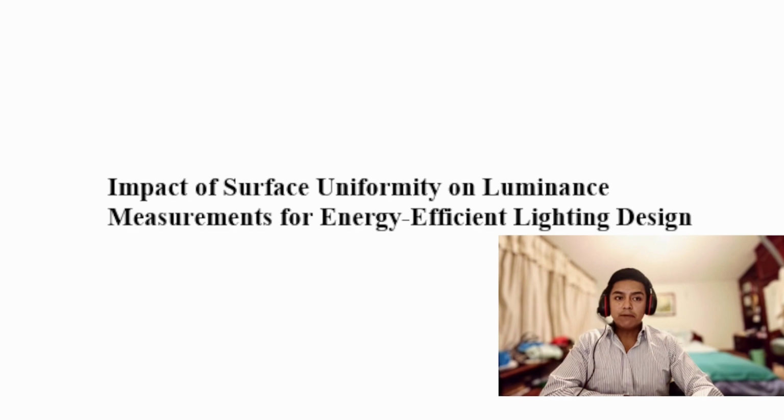Currently, methods that employ CCD or CMOS cameras are more prevalent in industrial and scientific fields due to the shorter time it takes to measure luminance. The pixels that make up an image are assigned luminance values through software, generally in grayscale. To calibrate these devices, techniques such as grading boards are used, allowing for multiple exposures and the assignment of a defined luminance value. In the work developed in, the calibration is performed similarly, but also employs a colorimeter.